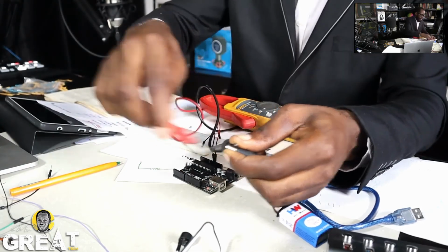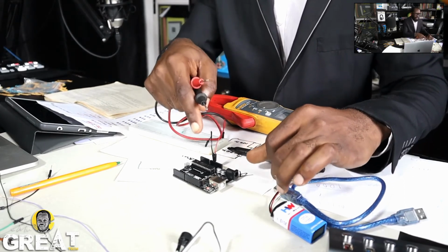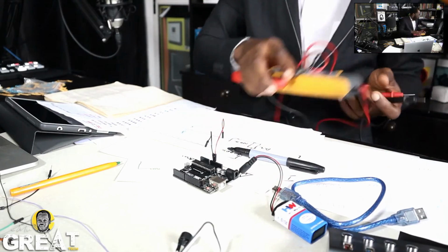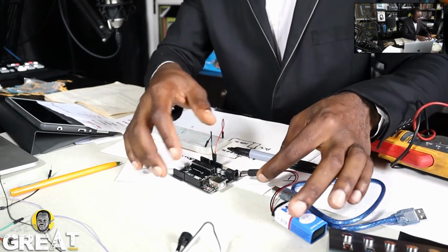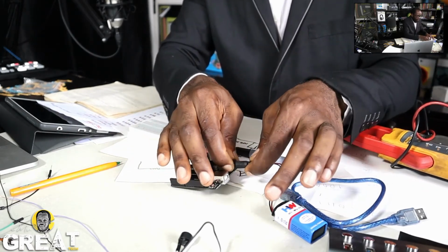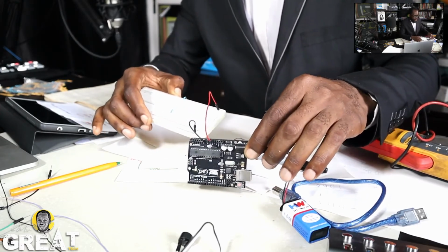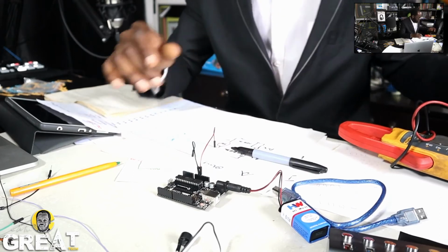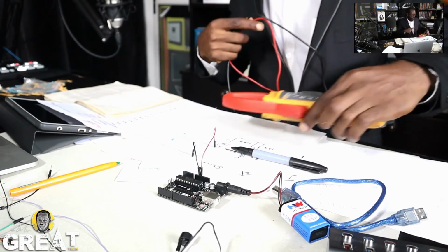So I use it to power my Arduino from here, which has a regulator that brings it down to 5 volts. So Arduino has a voltage regulator that will bring the 9 volts to 5 volts. So that is it. So I connect it, so it's being powered now. As you can see, it's being powered now. So you can measure from here to here, from the end to the end of the pin. I have 5 volts out.